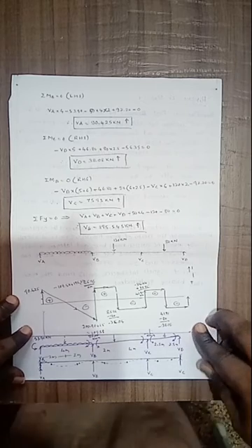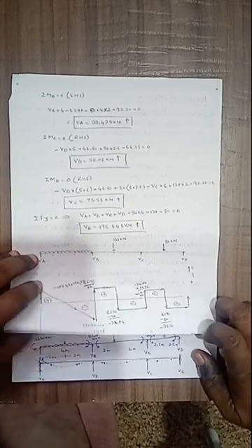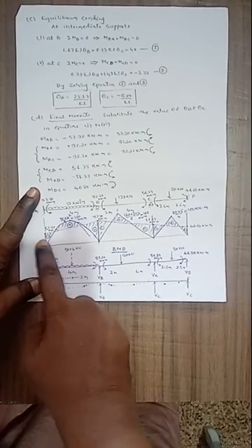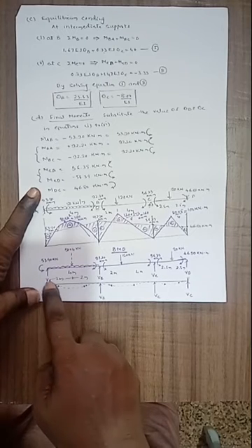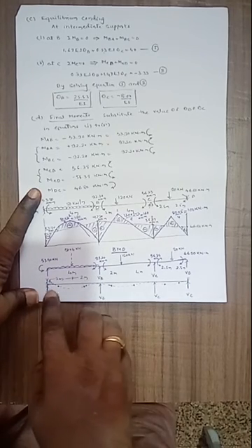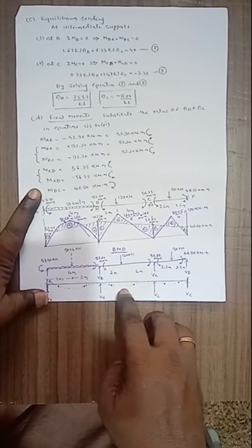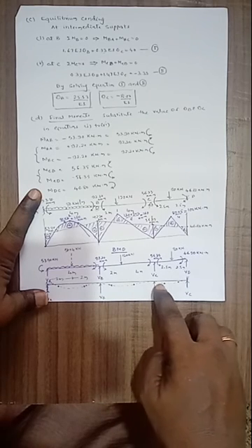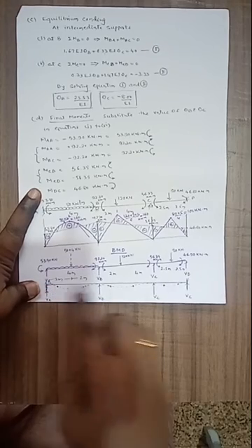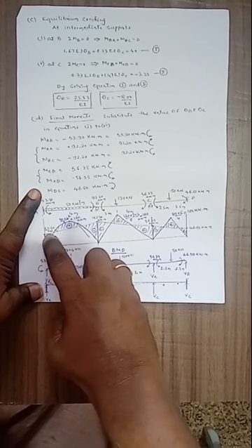If you want to draw the elastic curve for this, that is by observing the bending moment diagram. Here by observing the bending moment diagram for this beam, this one is the elastic curve. Here this one is hogging moment at the support. Then here the deformed shape of the beam, it will undergo deformation due to external load. Here this one is hogging at the support, sagging at the center, again at support hogging, at center sagging, then at support hogging, and the slope at the end supports, both the ends are fixed, the slope is 0.